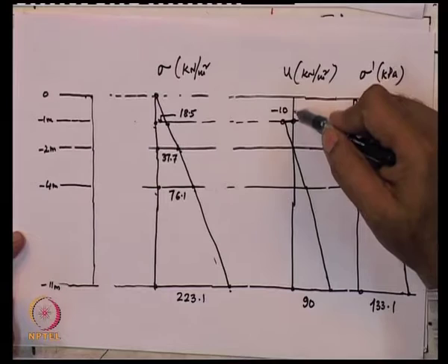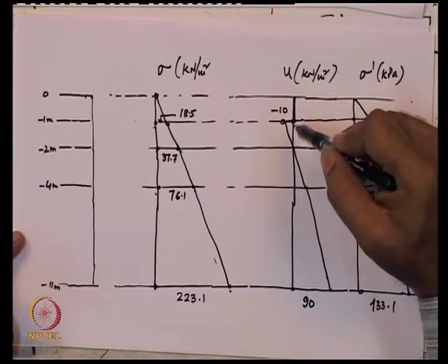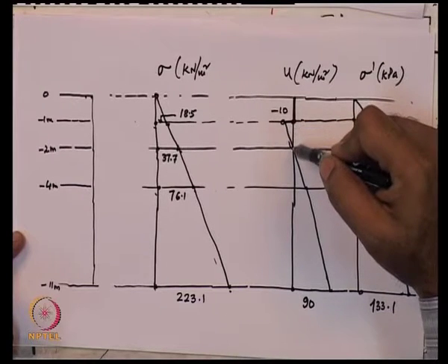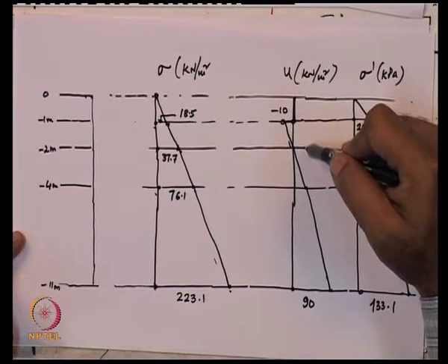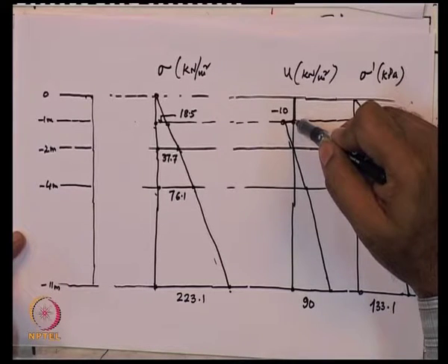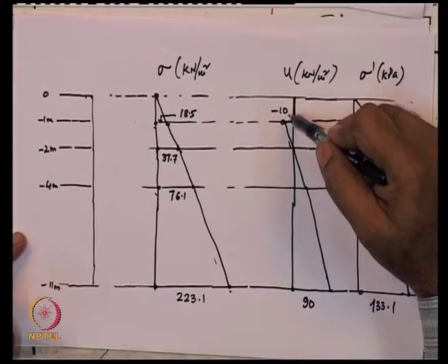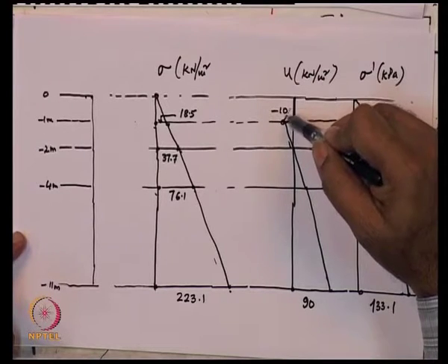And in the case of pore water pressure, here this is the capillary zone, the saturated capillary zone. So minus 10 kilopascals is obtained. What we discussed in the previous lecture indicates that as it comes to the ground surface, the pore water pressure reduces to 0.